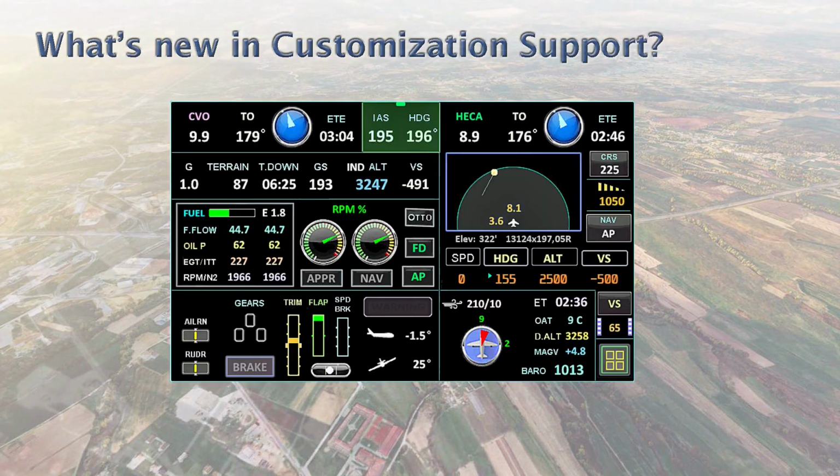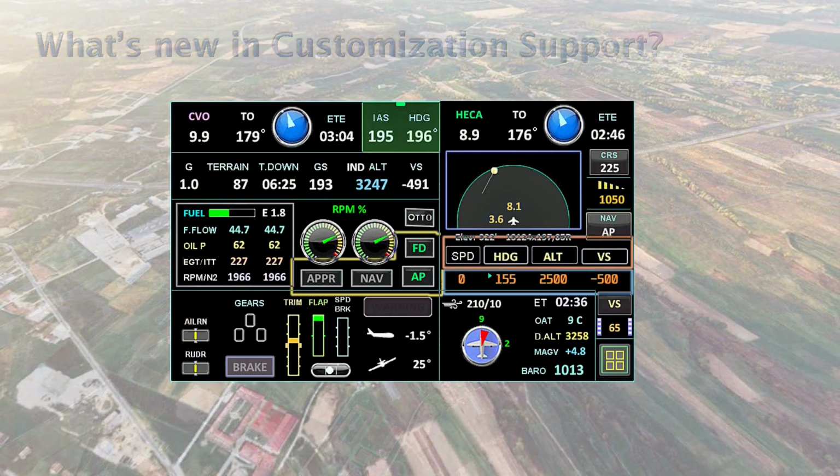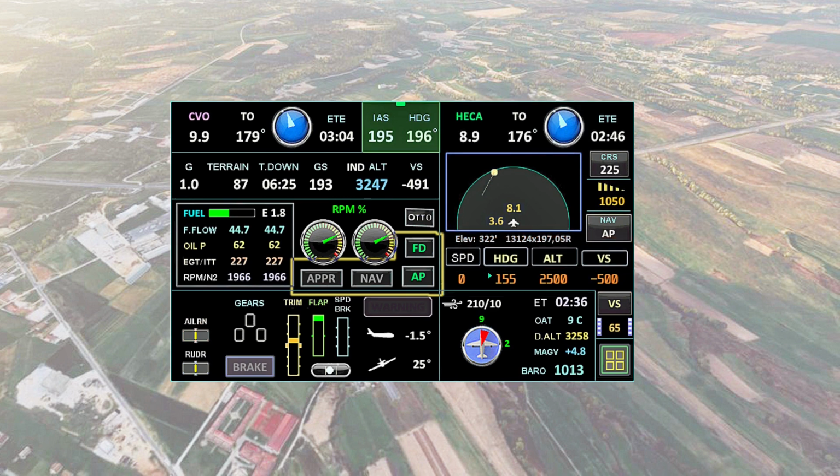First, there are now a number of objects on the situation page that can morph their behaviors depending on the particular aircraft. These objects are highlighted here. As you have noticed, they are all related to the autopilot. 8 buttons and 4 number settings in all. The 4 buttons on the left are now flexible so that you can modify their labels and assign them to control switches and lights from the cockpit of your choice. These on the left are limited to speed, heading, altitude, and VS.